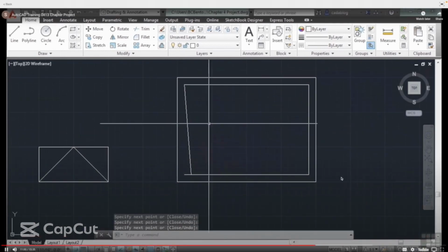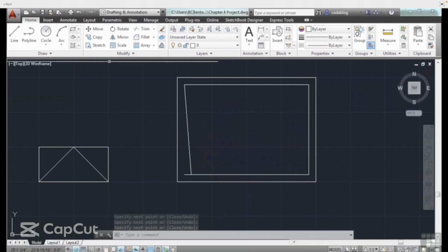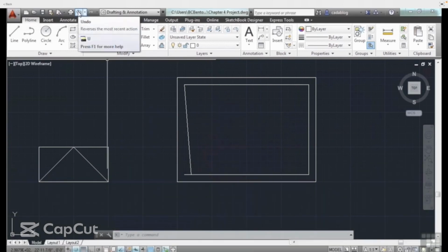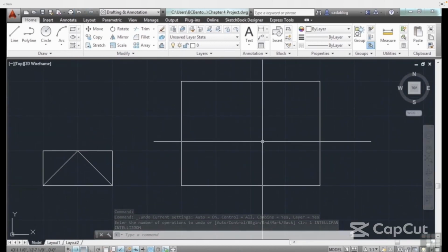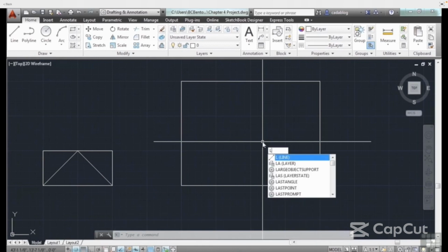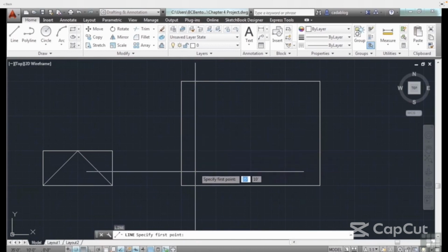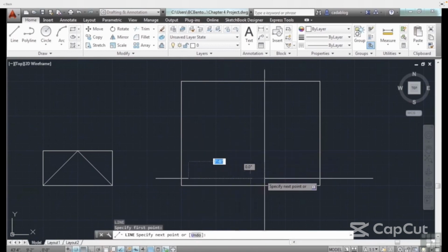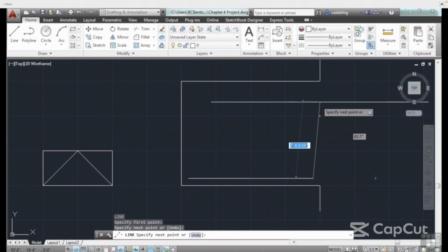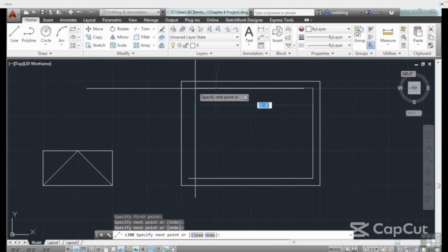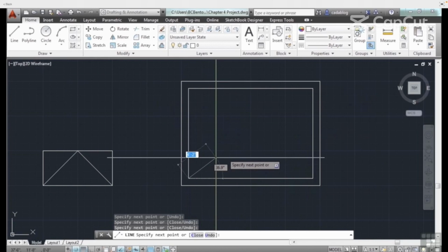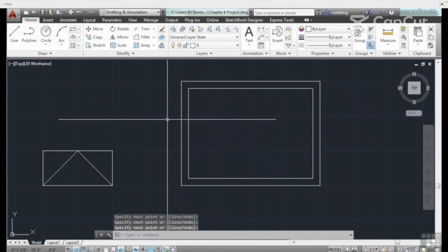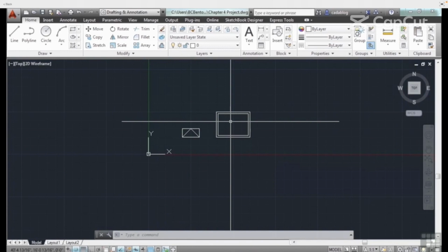Okay, I snapped to the wrong spot here, so let's undo that. Go up to your quick access toolbar and click the undo arrow. Well, it undid my whole inside box. Yes, because we did all of that in one command, in one function. So we need to draw that back. Draw a line, start the line command again. And let's draw. We'll keep the width of this box on the inside of the other box to just one grid space wide. When you're done, press enter.